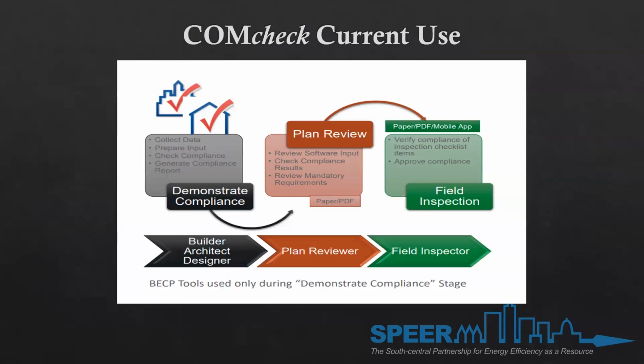This is a simplified version, but you need to show and demonstrate compliance at the very beginning. That's why you're building the energy model. So you collect the data, you prepare the input, you check the compliance, and you get the necessary generated compliance reports that are then turned into the city for permit. And that comes from a builder, an architect, and a designer. I'm not going to try to pull straws out of a bale of hay here, but what you don't see in that list is contractor. So that's something I've gotten calls about before: are these people allowed to do this model?